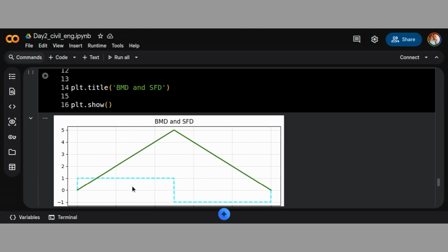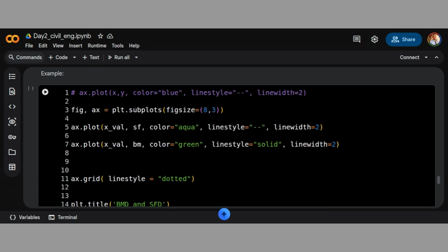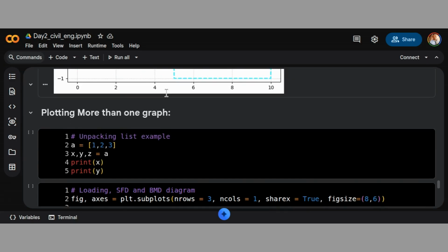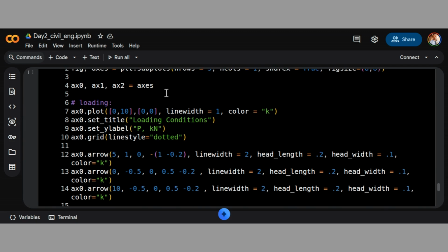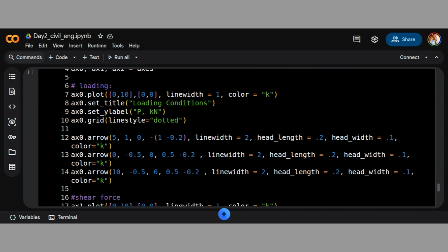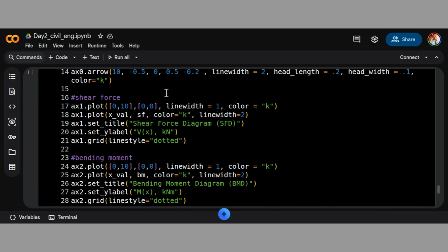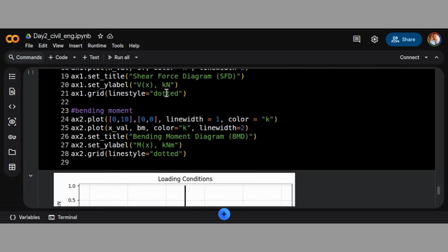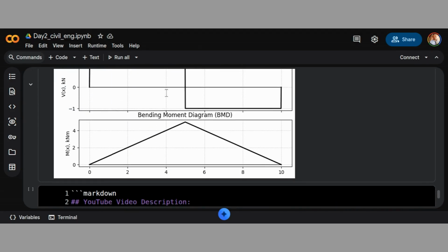You see the beam balance and the shear. You can change the balance, the color. You get this. All these are just Matplotlib manipulations. Computations are already done. So the same thing, you can look at loading conditions, and you can separate them. The shear force diagram, you can also look at them, and then the bending moment diagram, you can plot them singly this way.